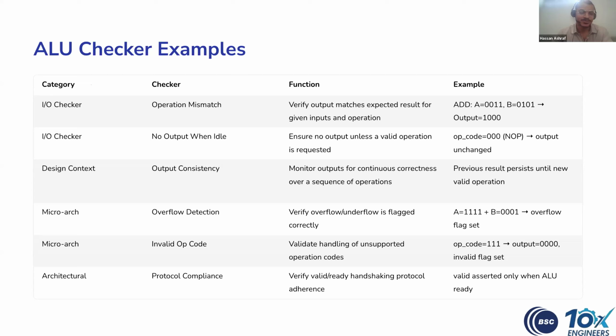Yeah, that's a common question, and it's the hardest part of our job as verification engineers. The answer is the thinking, not the coding. My advice is always start with the specification. Every line in the spec is a test case that the verification team has to test, and it's either an input or an output or a rule that you will follow to write the checker and your reference model. Each of those is a potential checker, and then think like an adversary. If I want to break the design, how would I do it?